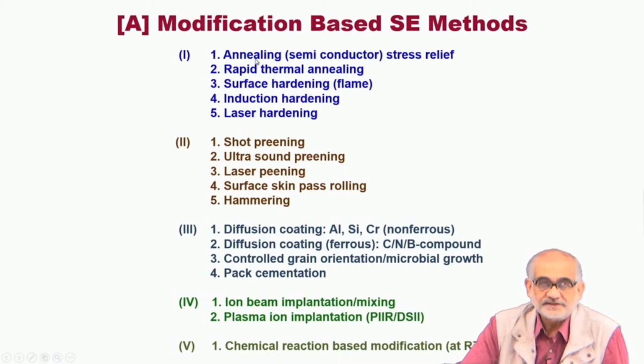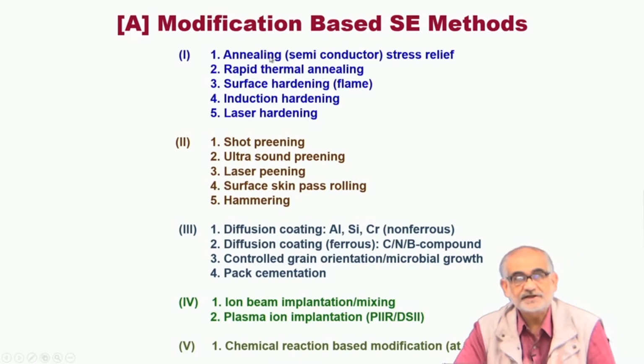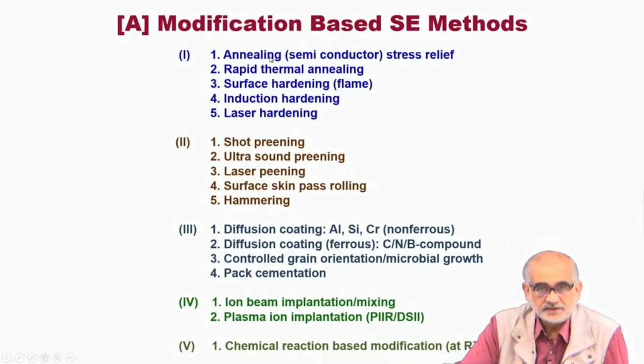For example, when you are changing the microstructure alone and not changing the composition by thermal activation, essentially you are exposing your specimen or the sample to elevated temperature, and diffusion may take place, certain phase transformations may take place, and in the process the surface acquires a slightly different microstructure. And this could be substantial or this could be marginal.